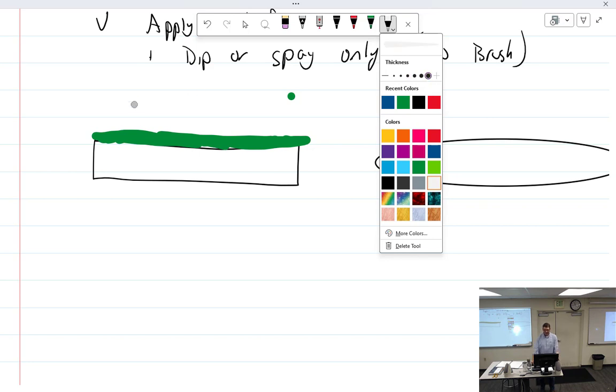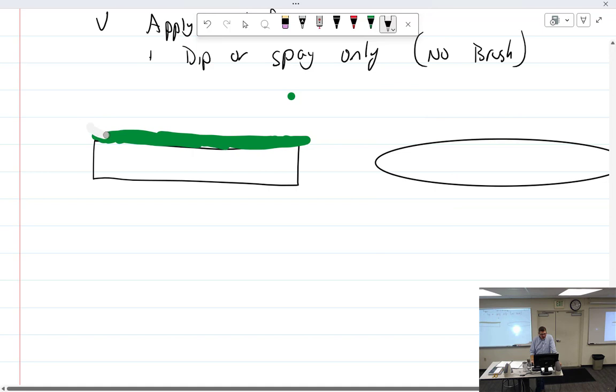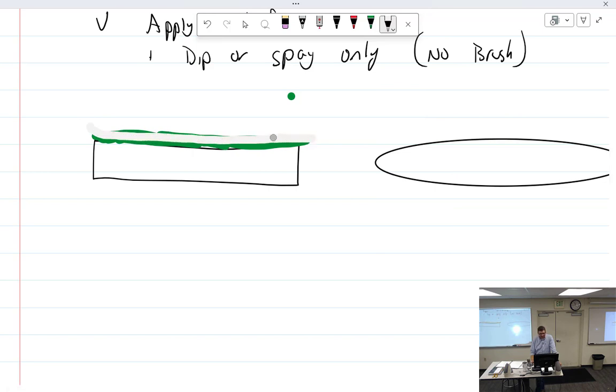All right. So then we're going to water wash, which is going to remove some of the penetrant, the excess, right? Then, if we want, we put on emulsifier. And the emulsifier is going to attack the penetrant from the surface down in time.